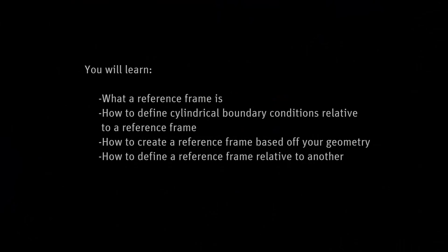In this demonstration, you'll learn about ANSYS AIM reference frames. You will learn what a reference frame is, how to define cylindrical boundary conditions relative to a reference frame, how to create a reference frame based off your geometry, and how to define a reference frame relative to another.